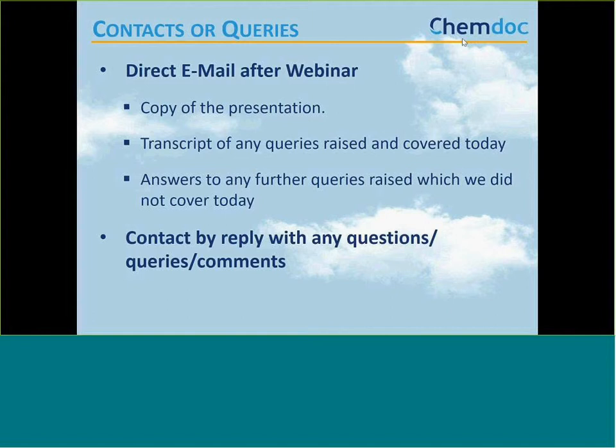And the second one, which was a question that had never been asked before, but it came in on email today, was, can you write a COSHH assessment without a safety data sheet? It's a funny kind of question, and I talked to consultants about it here. Firstly, we would say that really, if you have a product on site and you cannot source a safety data sheet for it, you should not have the product on site.